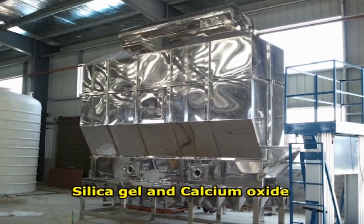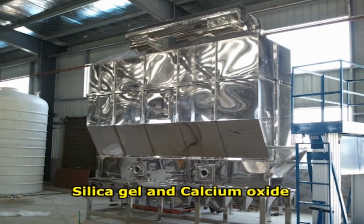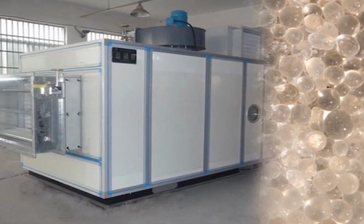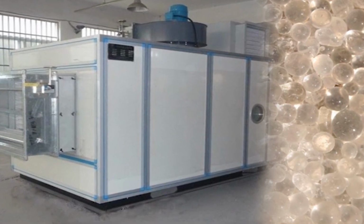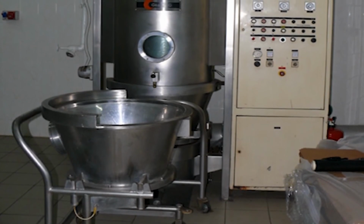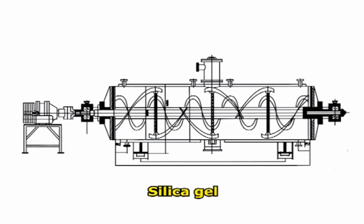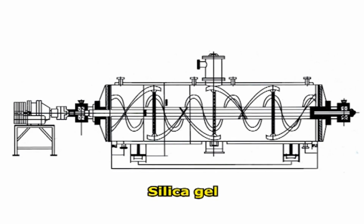Chemical dryers dry seeds over perforated metal trays that expose them to silica gel. Once the silica gel absorbs sufficient moisture, the silica gel is heated to dry it, thus making it active, a process called reactivation. This reactivated silica gel is again used to dry the seeds. Thus, the silica gel is rotated under the seed trays, continuously absorbing moisture.